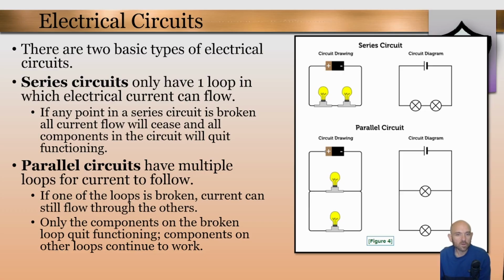This is why your home is wired in parallel. You can turn off one light without causing every other appliance and light in the house to stop working. Selecting the right circuit type is crucial for system design. Series circuits are great for simple devices or for creating one single control point, while parallel circuits are necessary for building robust systems where reliability and independence are key. Knowing how to combine these layouts allows for the creation of incredibly sophisticated electronic environments.